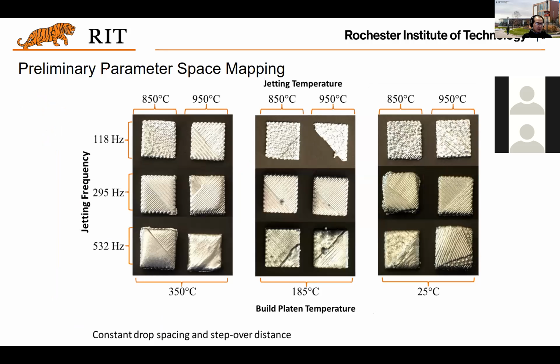Also, other parameters like the temperatures, build platform temperatures and all, versus the jet frequencies. So again, you could find which are the best combinations of these parameters, right?